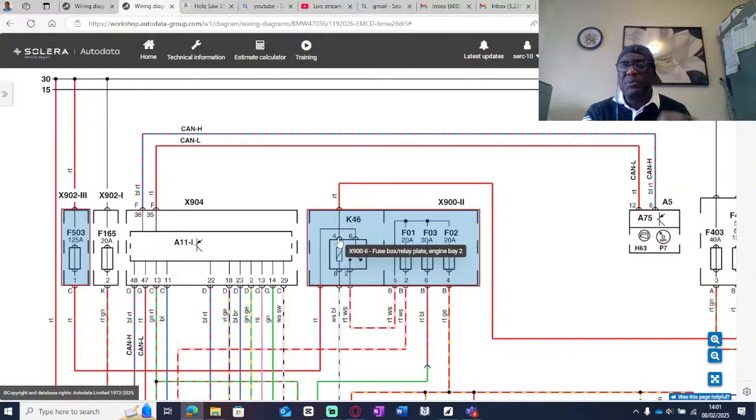So here is my tip to you technicians. Whenever you are diagnosing a relay, you want to look for those two powers. Remove the relay completely, pull it out, and then check the 4 pins. If you don't have a diagram, but your relay has a diagram, you can see which one is your pin 30. On your relay, that could be pin 30, that's your permanent live, and then you'll have pin 86, if I'm not wrong, as your power.